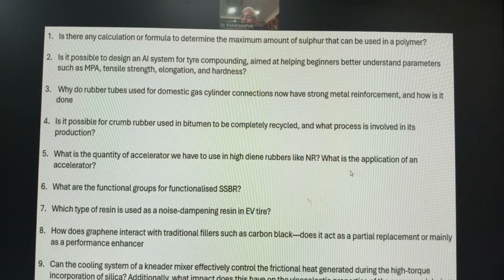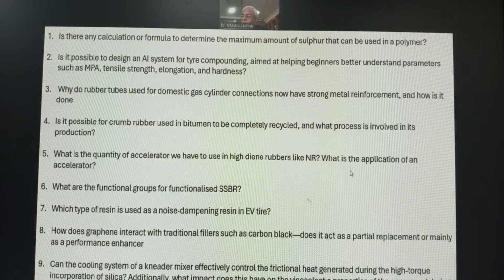So even if there is a crack, it's a hose type. You have an inner tube. The inner tube generally is nitrile PVC or oil resistant polymers, and the outer tube is weather resistant, basically either nitrile PVC or rubber, and then braided hose type. Then you have an inner liner, braided hose, and then you have a cover. That's exactly the way the hose is manufactured.